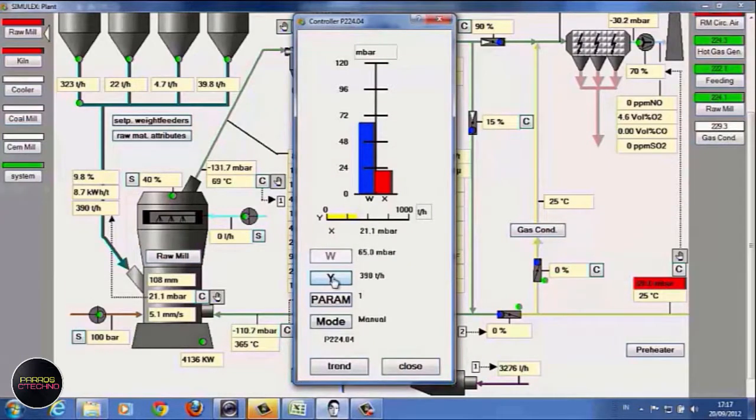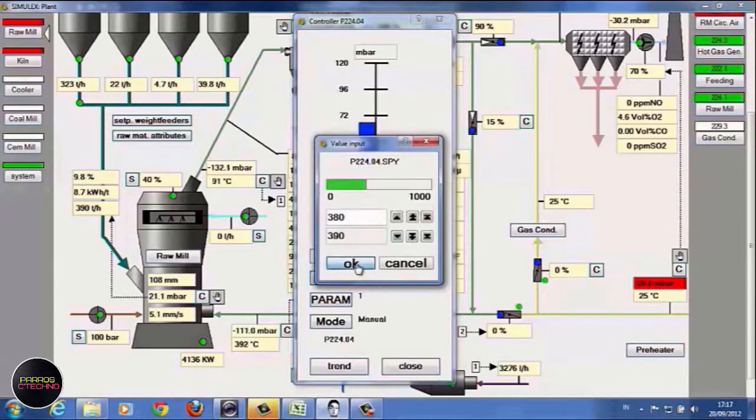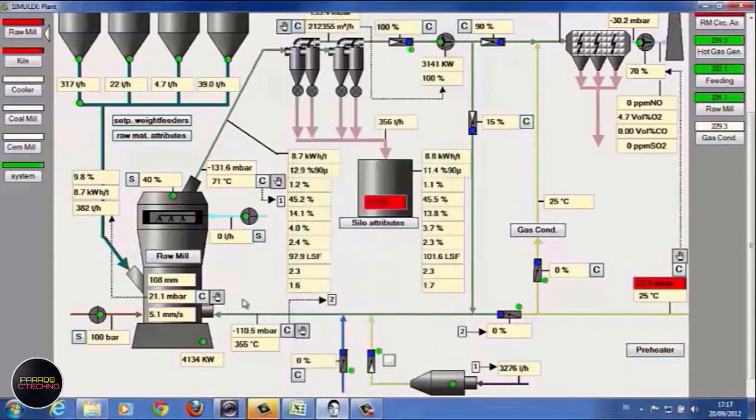Because the moisture content here is still quite high, we lower another 10 tons for feeding. If the vibration increases, the hydraulic pressure must also be lowered. LSF is all in with its standard, 380 tons of feeding, then the bed material is still normal. Now, wait until it reaches 40% or 50%. Why does it have to be 50%? Because for continuous blending like this, the blending can be effective if the raw meal stock is above 40%, below that the blending effect is not good.